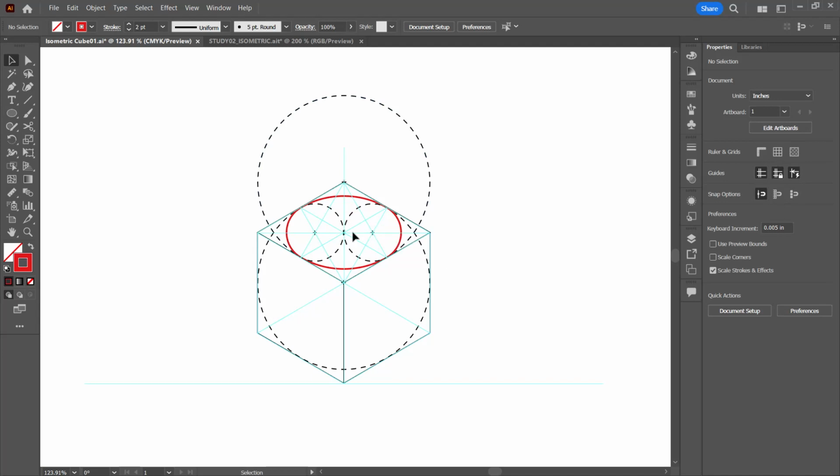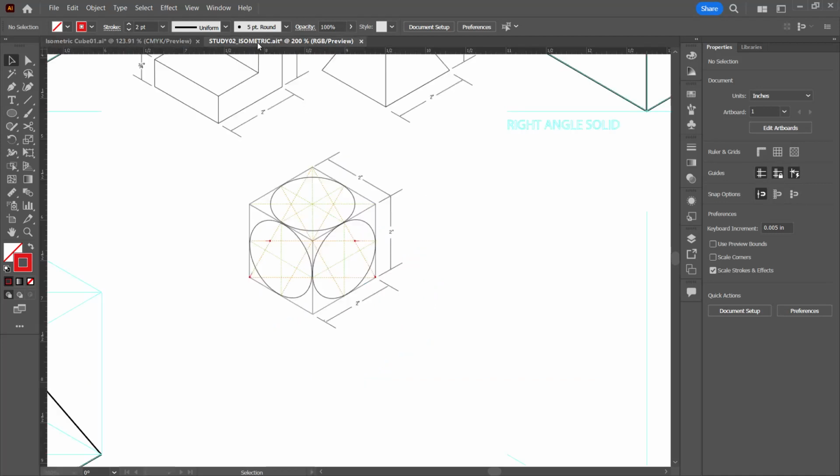So again, anytime you've got this, if you think about the midpoints of your edges, creating those creates the places where you can then create your center points for the radii you'll need. All right. And if you draw this, you can just see that the ellipse is going to lay and contact on all four of these points. Okay. So let me jump back here.